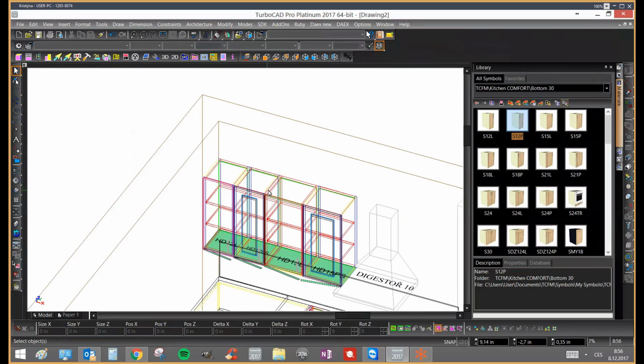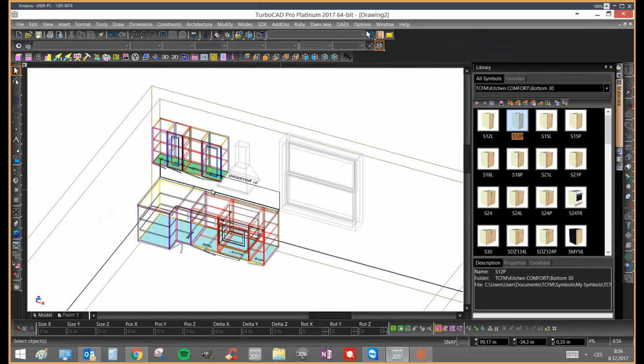If you draw the polyline and generate something, the polyline isn't there anymore, but there is the generated worktop or the ramp. And then you just select the ramp or the worktop and change the material. Is that what you meant? Yes, you can change the polyline.